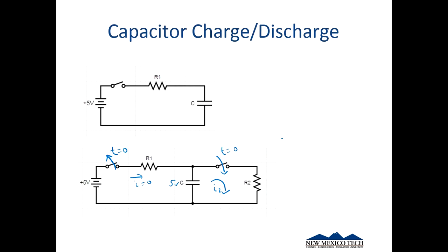And we run into the same sort of thing where we are discharging this current through this resistor. Initially that current's going to be high, and it's going to drop off, in I and T, because we have a big potential to begin with, 5 volts. And remember, this is just storing energy. As we discharge that current, I wouldn't say we're using it up, we're dissipating a bunch of it as heat in this resistor. And so the current drops off, and that's basically what we have. Okay, so that's a capacitor.